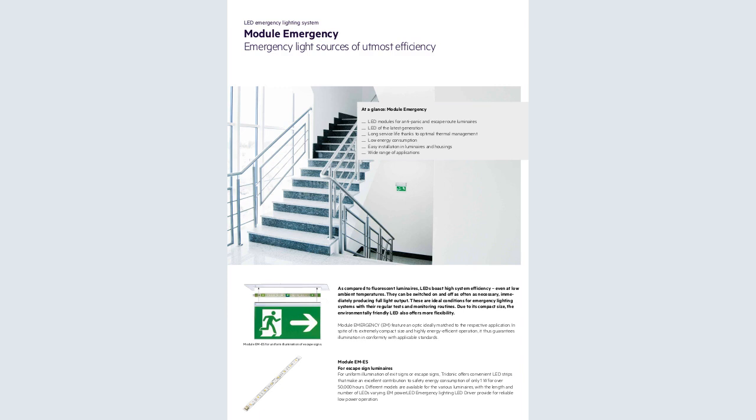Salad, I answered your question in the group. Some of the lighting installations need emergency, need standby power. There are things like the emergency lighting. And remember, we said that a special installation like the ones for theaters is not called emergency lighting. They need standby installation in that they should not have their power off. In case of interruption of the normal power, the power should come on immediately. So those are the two areas that need standby installation: the emergency lighting installation and the special installation, like those for hospitals and theaters, and where there are high risk operations and works to be done.